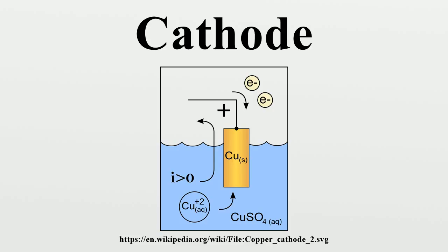The main reason for using an indirectly heated cathode is to isolate the rest of the vacuum tube from the electric potential across the filament. Many vacuum tubes use alternating current to heat the filament. In a tube in which the filament itself was the cathode, the alternating electric field from the filament surface would affect the movement of the electrons and introduce hum into the tube output.